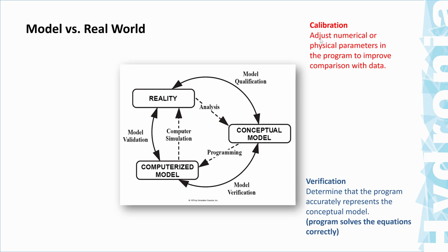It can be measured velocities or depths for specific events. It can be a wide variety of things that you could use for calibration. What you do is adjust the model, compare, and continue adjusting until the comparison is satisfactory. When it is satisfactory, you consider that the model is calibrated.